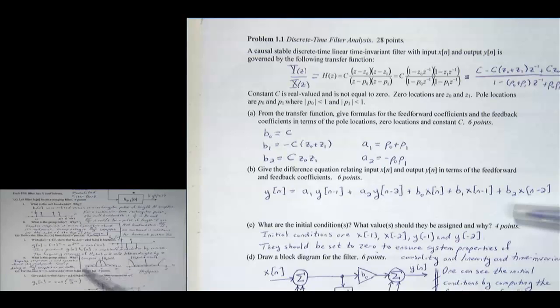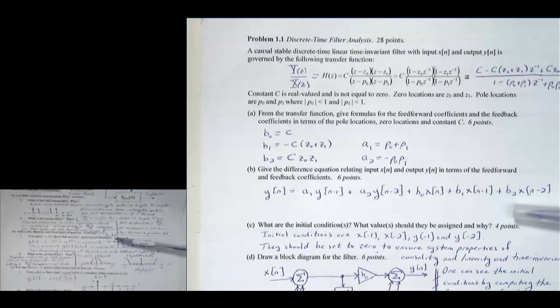All right, so there's another trick here. If I want to change a low pass to a high pass filter, I can just multiply the coefficients, or the impulse response, by minus 1 to the n. Again, we have symmetry in the impulse response. Here I show you the impulse response. So I have odd symmetry about the midpoint. So this has linear phase, generalized linear phase, and the group delay is N minus 1 over 2.